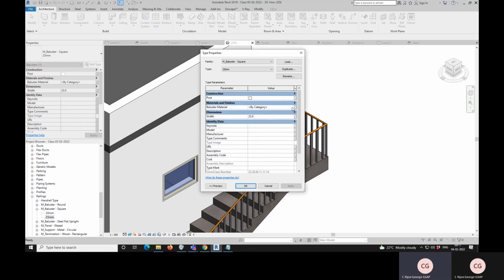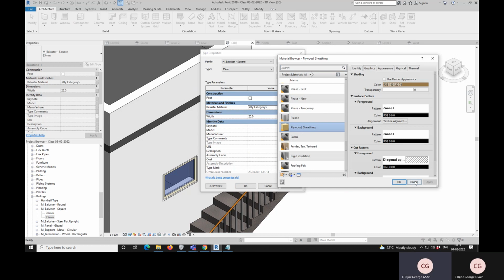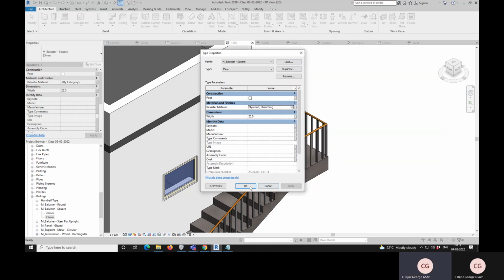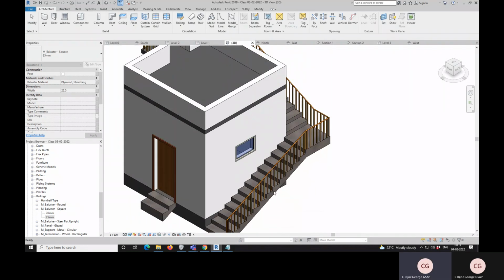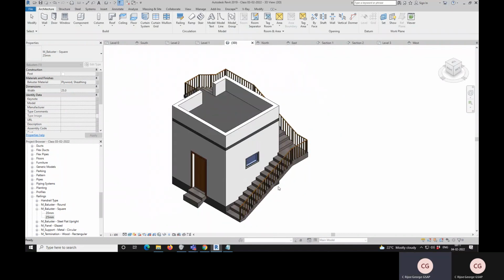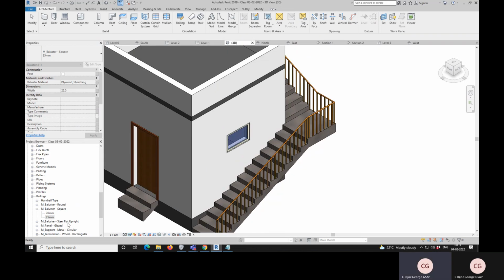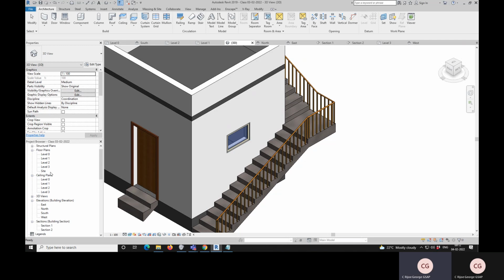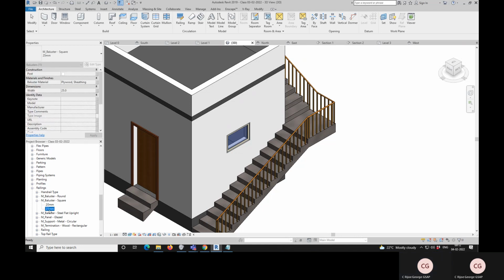Here we can use the material over here. So you get the color for it. So only for applying the railing material, a baluster material, you have to be a little careful. You have to go to library. Where is it? It is in library. Library is far below all these things. In that you have to go to railing. In railing you have to select the kind of material balusters used inside.